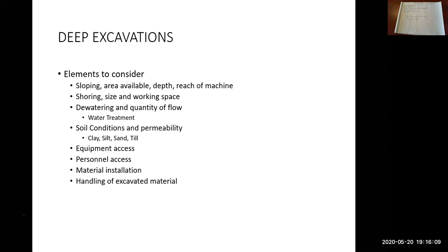So another item there is dewatering. So if you're digging deep enough into the ground, no matter where you are, you're eventually going to hit the water table. So you have to deal with the water. You have to pump it out, you have to get rid of it so that you can build the foundation of whatever you're building. So you typically cannot install, like, a bedding gravel in standing water, so in puddles of water. The ground has to be dry.